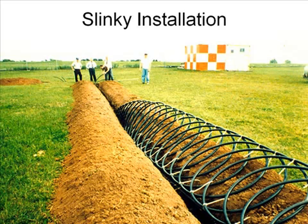So if you've got a lot of soil up on top of the ground, that means that you've got a lot of air below the ground. And even if the thermal performance is all right, that soil is going to subside in those trenches, and you're going to have to come back in and do grading, and you don't want to do that. This looks like the standard project at OSU: one guy working and 4 guys watching.